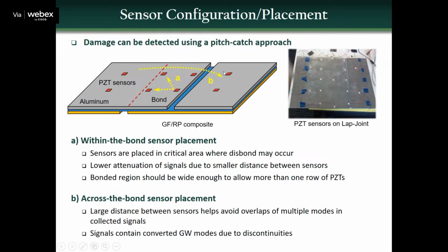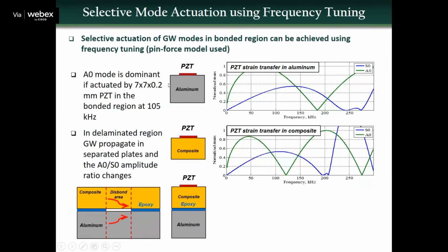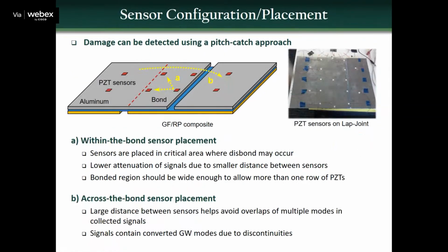We work on this technique using the pitch and catch approach, similar to what we did in classical pitch and catch ultrasonic testing. Now you just use one as a transmitter and the other as a receiver, and then get the signals when it propagates from one TX to one RX.